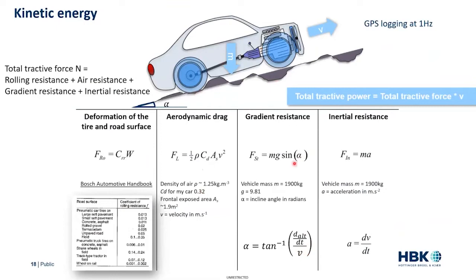And if we sum those together, then we can actually calculate the theoretical force that's required. And if we multiply that by velocity, that gives us the tractive power. So GPS can give us a relatively accurate assessment of the power from the vehicle. It depends generally in a car on how many people you've got sat in it and whether you're towing anything. They're the biggest influences, the mass. But typically we can get 5-10% probably the worst estimate. So between 5 and 10% accuracy on that.